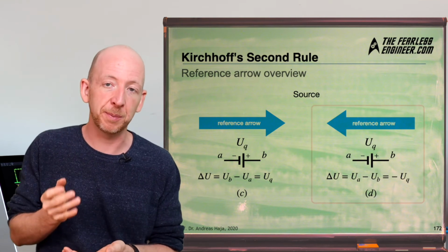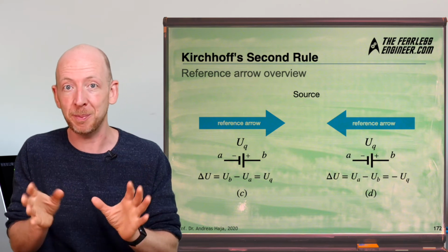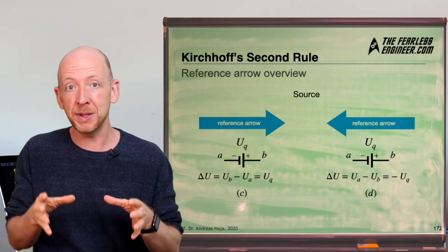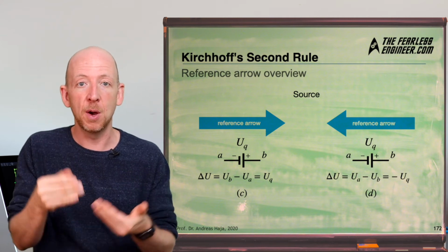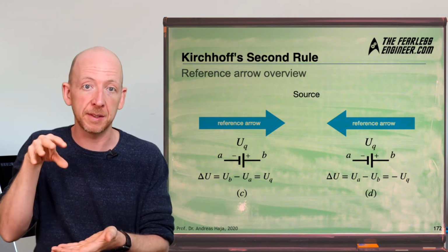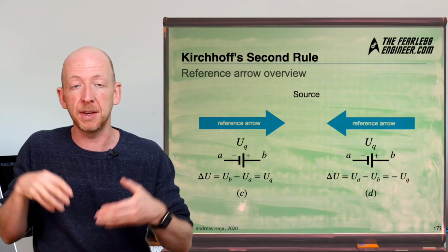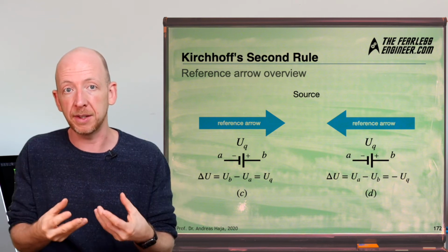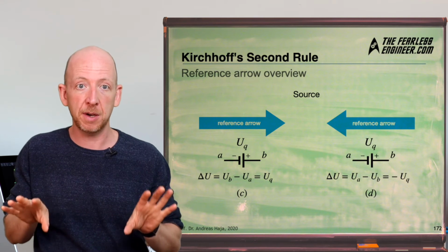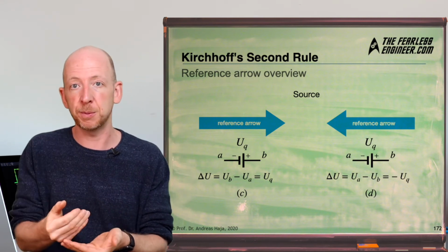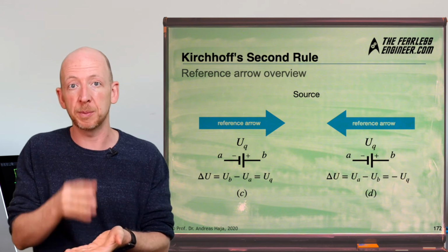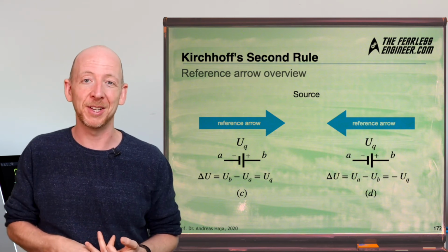And in order to reduce the potential for errors and to avoid confusion, my personal tip to you is to always start at the source and proceed in the direction of current flow when moving through a loop. In this case, the source voltage is always positive and the resistor voltages are all negative. In case of a branched circuit, however, the different currents can also have different signs, which you encounter within the same loop even. But this is something which we'll look at in later videos.